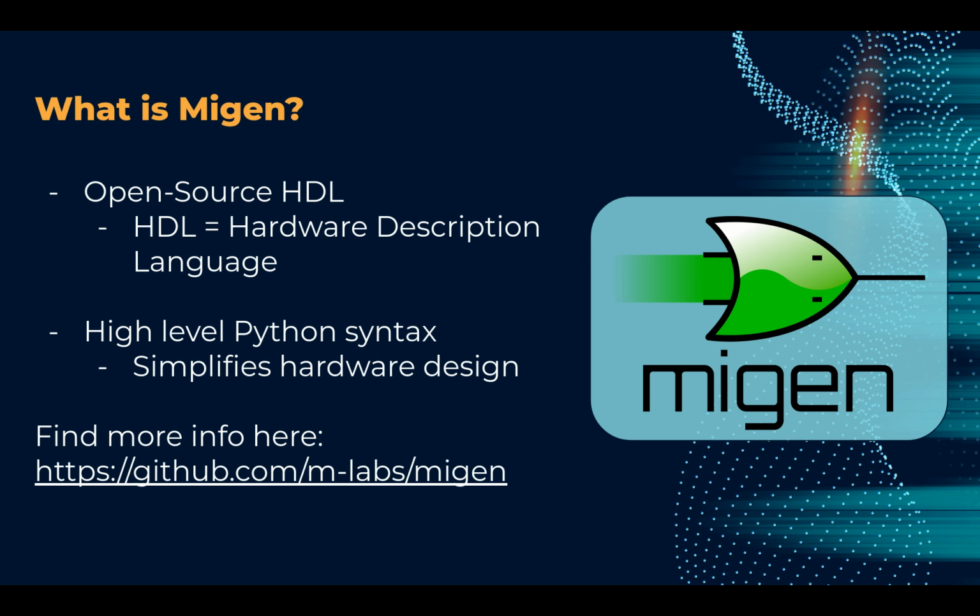One of the key features of MiGen is it allows the automatic generation of hardware structures from these high-level descriptions. This is important because it means designers can specify the functionality of a circuit using their Python code, and MiGen in turn will generate the Verilog or VHDL code automatically. This reduces the time and effort needed to create and modify digital systems. There's also a couple other features like partial reconfiguration, which means you don't need to reconfigure the entire system if you change one little part of it. It's a powerful and flexible tool which simplifies the design process. Great tool for this application.